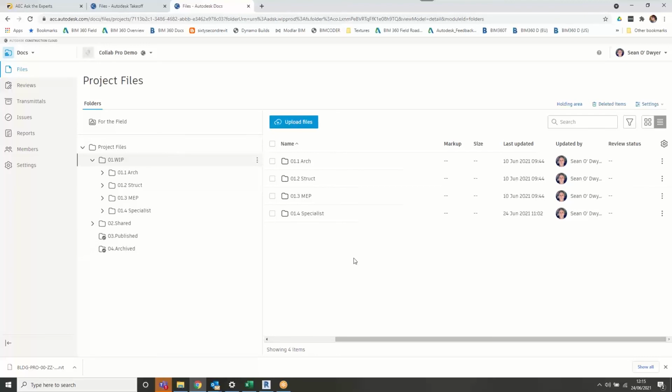Just be very cautious of that if, for example, you have an architect and a mechanical contractor who are engaging with Collaborate Pro, and they're linking in no problem, but your civil structural team don't want to have Collaborate Pro. What they do is they just upload it in and you link it through the desktop connector into both your architect and MEP Collaborate Pro models.